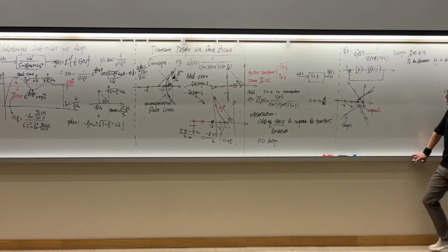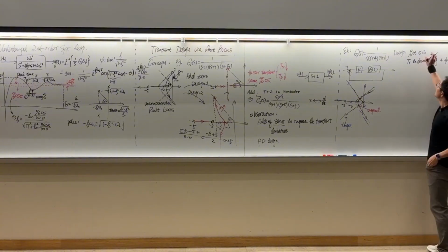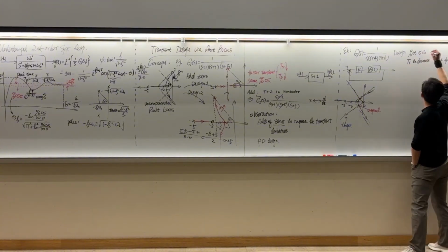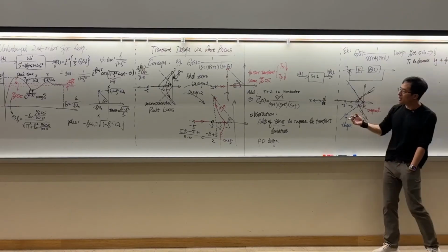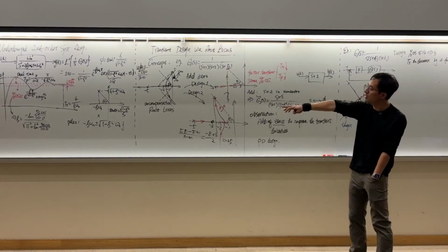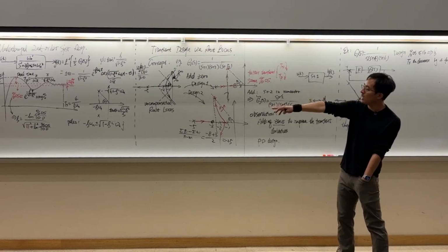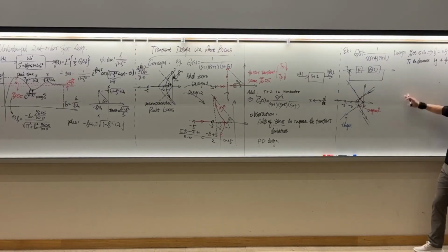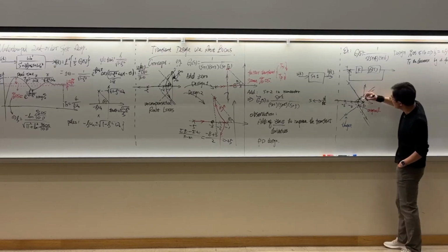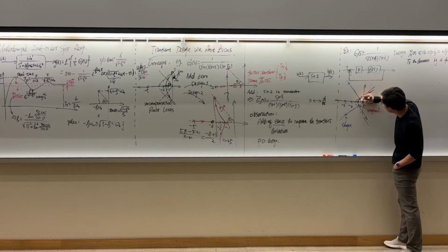Now let's look into some of the details. First, let's be more systematic. Let's translate this to zeta. If I know my percentage overshoot, that means my zeta from that equation on the left can be calculated. I did it for you. It's going to be about 0.504. And then having a zeta means, make sure the screen is still captured. So if we know zeta, now let's work on what the zeta angle should be.